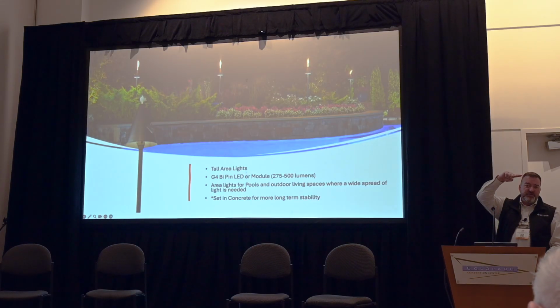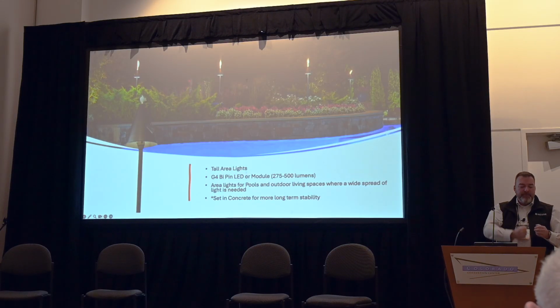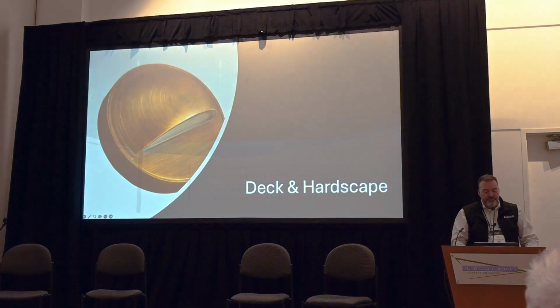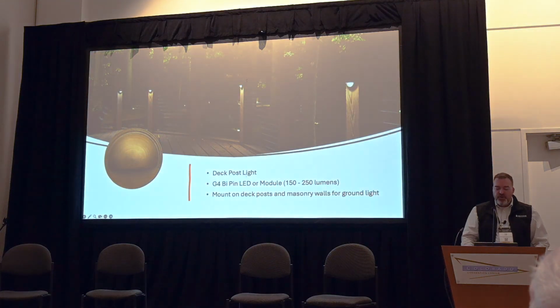Put in 18 to 24 inches of extra risers in there and put them in concrete because that'll stiffen everything up and they're not going to get knocked over and broken, because that always happens. Deck and hardscape lights, so putting lights in posts.